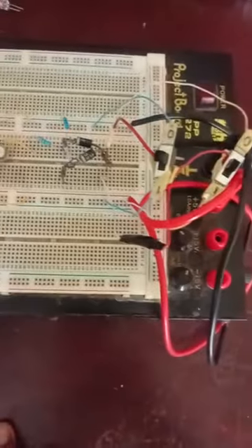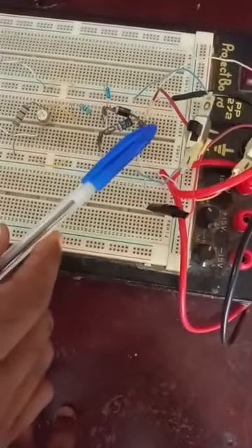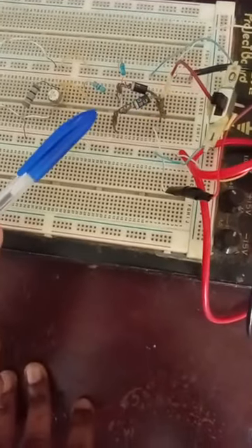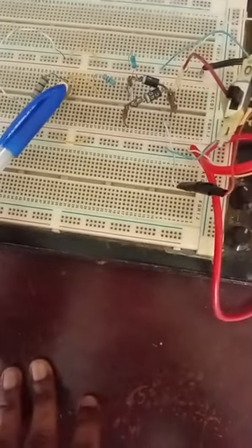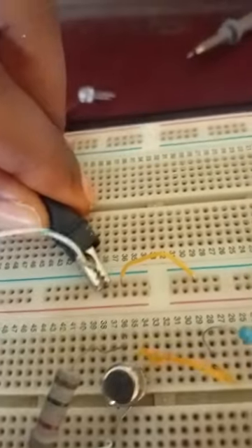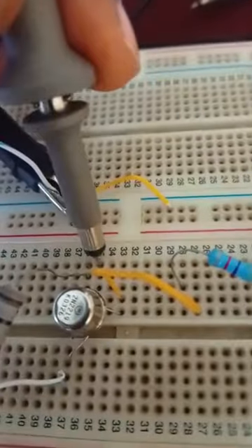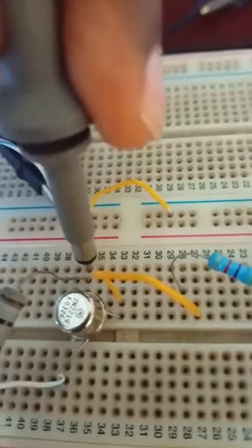Yeah, let's go. This is the circuit. We have the two switches. We have diodes, the positive connected together, the negative, that's the cathode side, feeding the base of the transistor. Then this is our oscilloscope. We use the negative of the oscilloscope to the ground, and the collector of the transistor goes to the positive. Okay, let's inject 5 volts to our circuit.